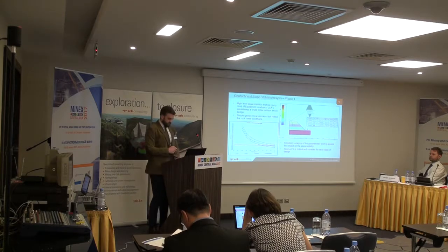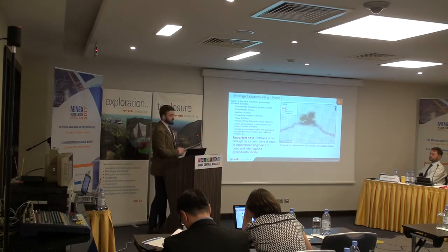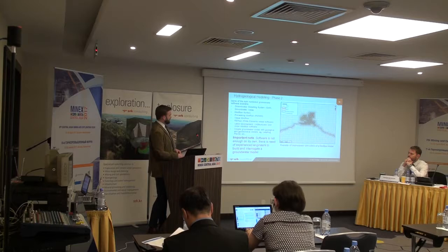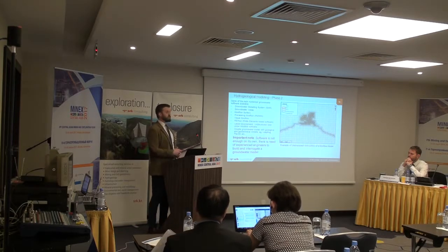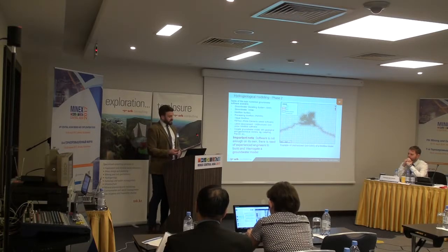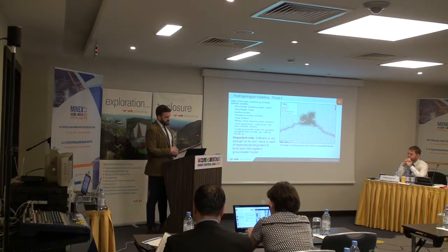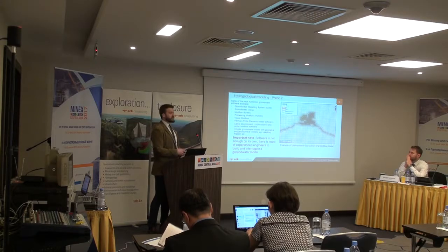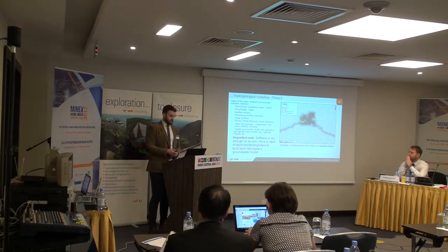And these are just some of the main numerical groundwater packages available that we use to understand the change in groundwater conditions. And I've touched on this before. It's very important that the software is not enough on its own, and there is a need for experienced engineers to build and interrogate a groundwater model. And the example I have here on this image is an unstructured grid, USG, of a MODFLOW model, which works out the change in groundwater conditions over the life of the mine.